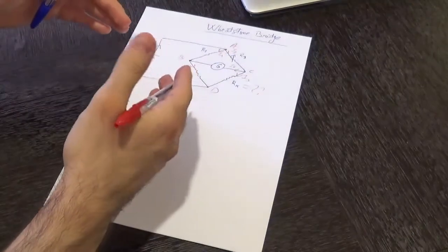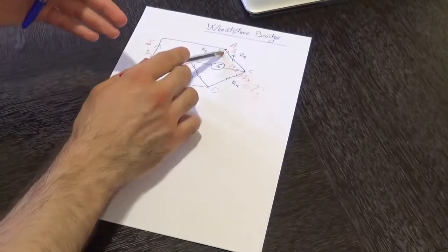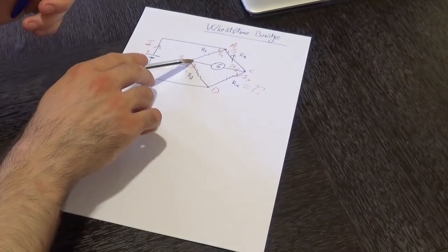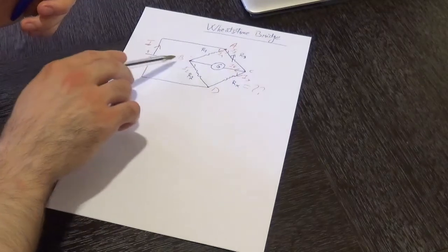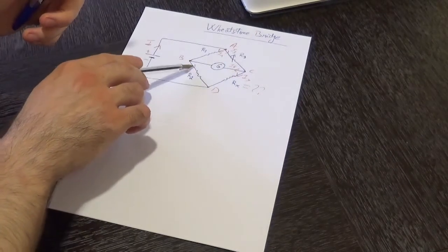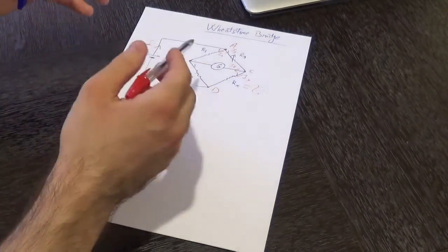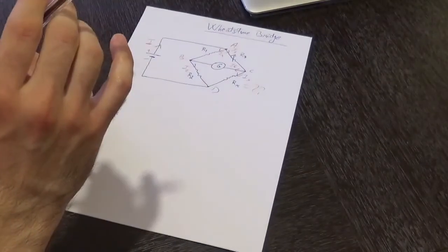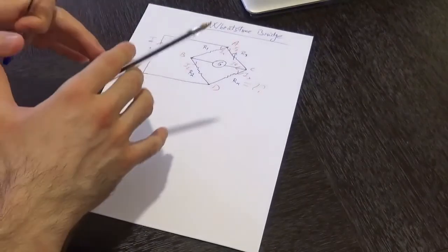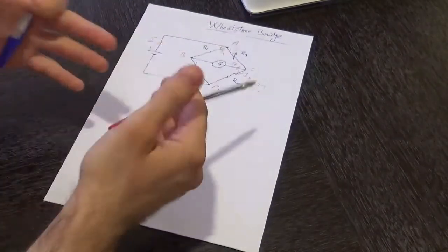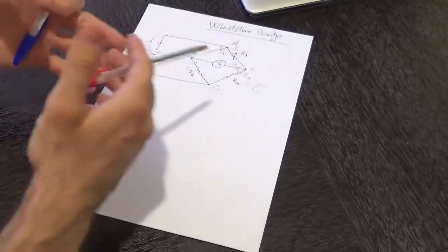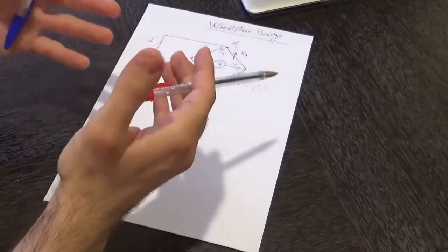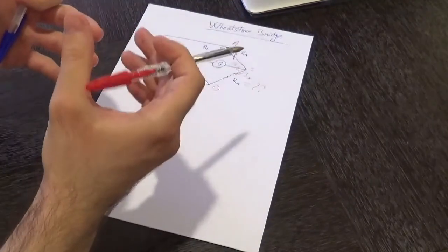Now in a similar manner, you could have also chosen the fact that I1, once it reaches node B, can also split into IG, which is going to flow in that way, and I2, which is going to flow downward through R2. So basically the direction of the current in that case is not going to matter, as we have seen previously, since what matters would be the sign that you obtain for that electrical current. In case you obtain the positive sign, that would imply that you have chosen the right direction for the current, and if you have obtained the negative sign, therefore you need to flip the direction and